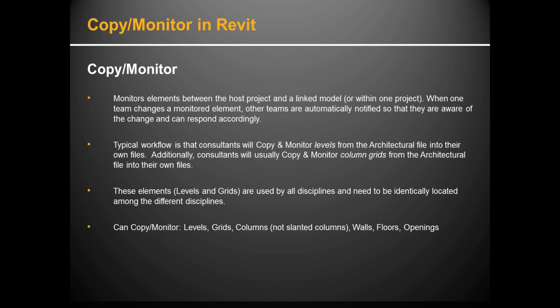These elements, the levels and the grids, are basically used by all the disciplines, and they do need to be identically located among the different disciplines, so that the electrical engineer is using the same grid lines as the structural engineer, who is using the same levels as the architect. Everybody needs to be coordinated on these items.